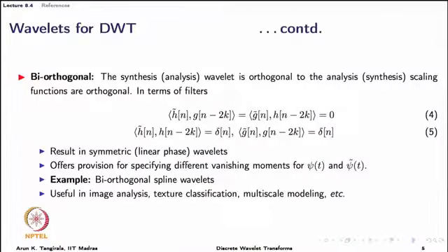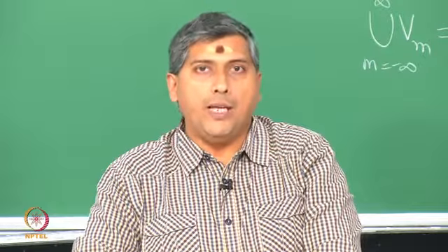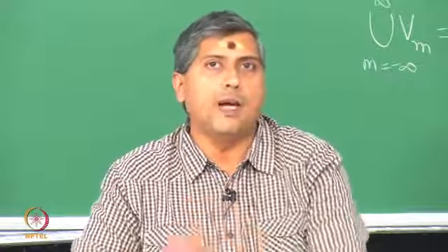Moving to biorthogonal wavelets, which we did not discuss in detail in the previous lecture, but I did mention this term when we were talking about synthesis filters after we discussed the decomposition filters. Remember, we imposed orthogonality at the time of designing the decomposition filters themselves. That is, we said Wm should be perpendicular to Vm. But suppose I do not do that.